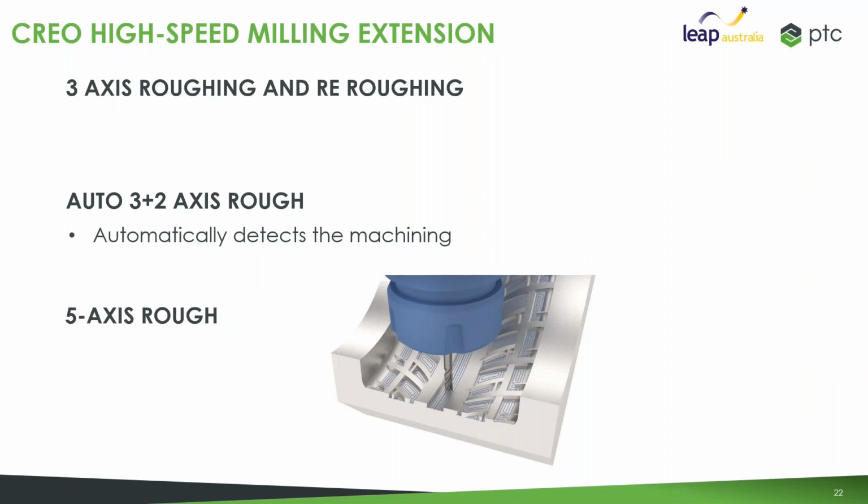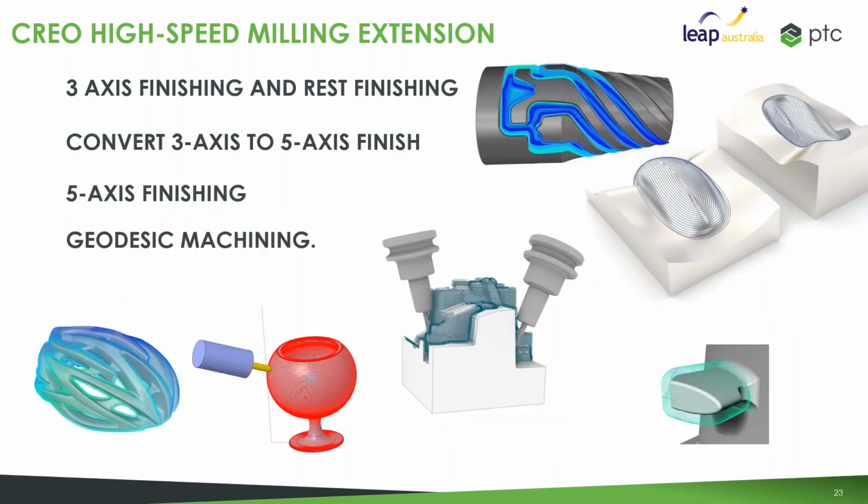It offers very powerful roughing, especially constant load 3-axis roughing, conversion of positional 3+2 5-axis, and also simultaneous 5-axis machining. It also has very good quality surface finishing tools, and it can finish very complex parts while keeping the surface quality.